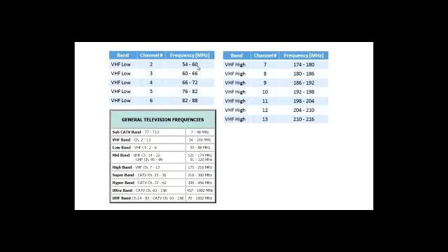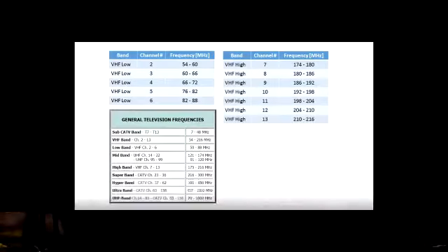So you can see there's a 6 megahertz space out of the whole frequency spectrum. 6 megahertz is going to be designated for one channel. All right, next channel is going to occupy the next 6 megahertz. All right, channel 3 goes from 60 to 66 megahertz, and so on. You see there are 6 megahertz slots. So therefore, that will also enable you to understand the frequency division multiplexing, okay?